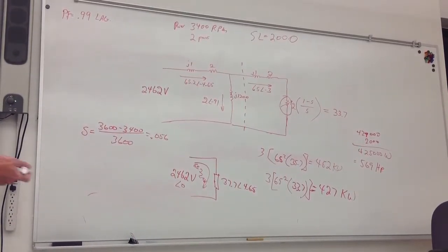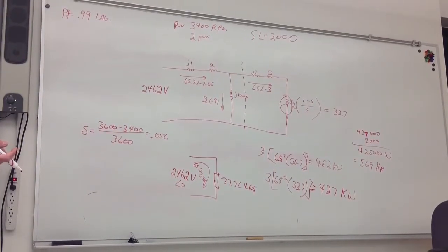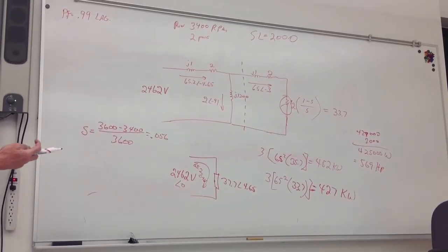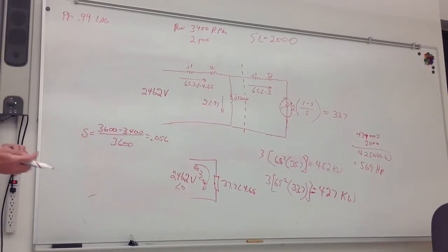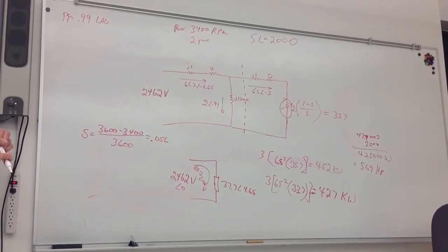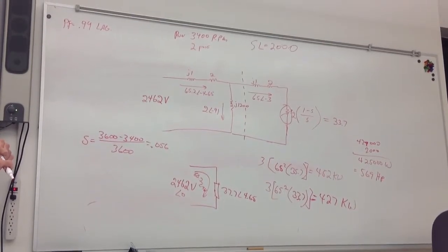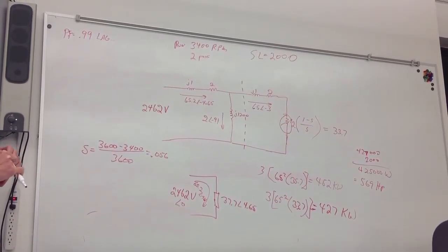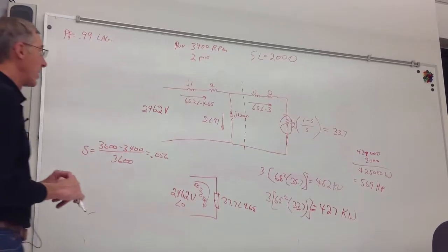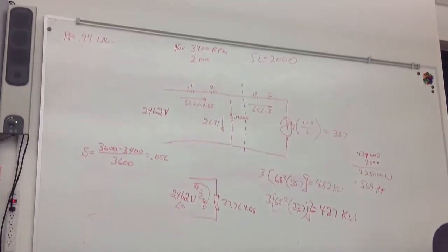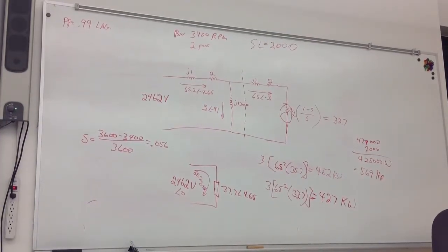So it's like a perfect motor that makes a whole lot of horsepower for us? With our power factor like 0.99. Well, tell me what you mean by perfect motor. I mean, this is unrealistically high, not much loss. But this is a real model, so this isn't a perfect motor. If we could build a motor that well, we could get this condition. My problem is I probably made this too high. A real motor would have more magnetization current than this one has.